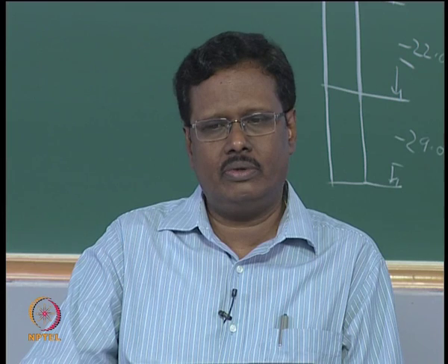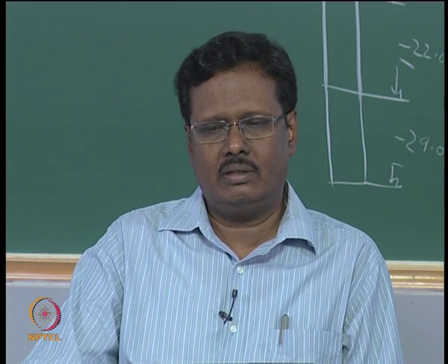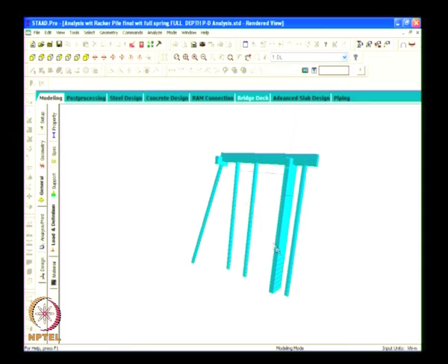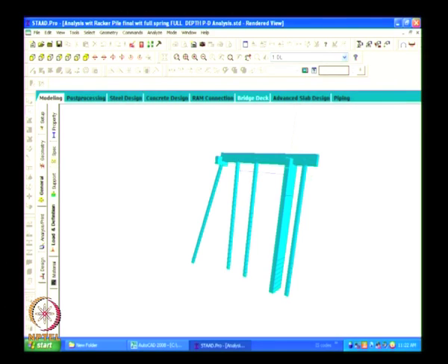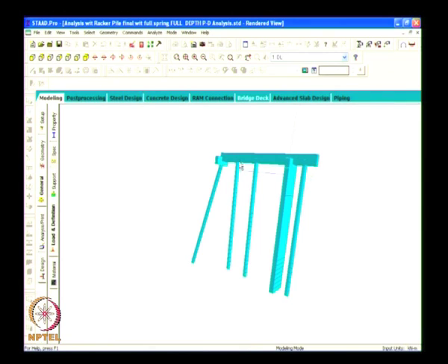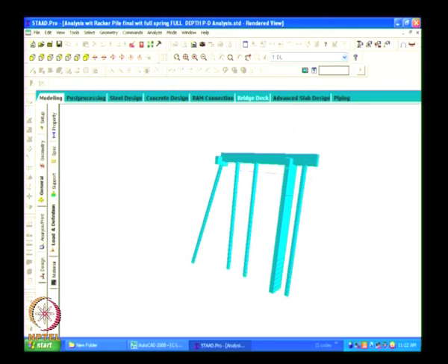You have understood the view now, here there will be a dredge level, this is 17.5 meter. Back side there will be full soil, but there is an active wedge going here. So this soil will be sliding. Suppose the diaphragm wall is not there, if you fill up the soil, what will happen to the soil? Soil will slide down, that is that 45 degree wedge we are assuming, and the soil itself is sliding, it will not offer support. That is why we are not offering support above this active wedge line, only below that we are putting the spring.